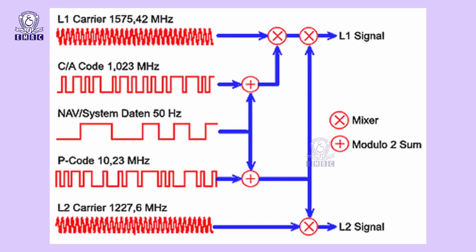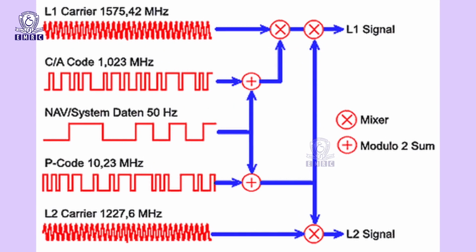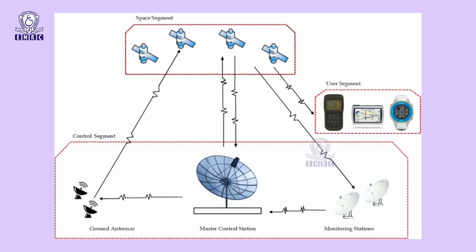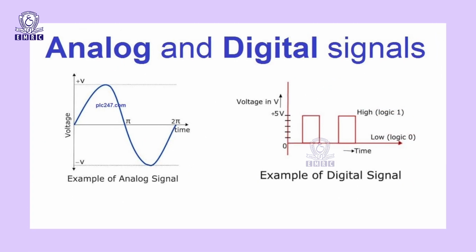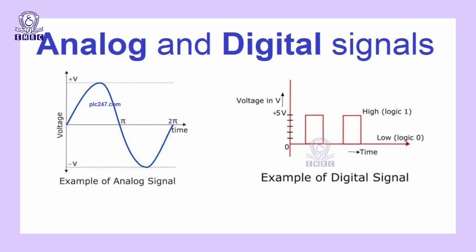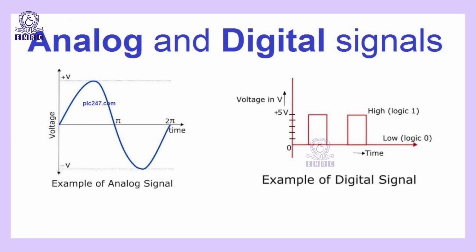Hardware bias errors. Hardware bias errors can be differentiated, as there are different types of satellite bias present. Upon signal transmission, the GPS signals on each carrier frequency and among frequencies are imperfectly synchronized due to the different digital and analog signal paths corresponding to each signal.